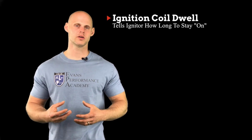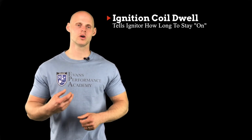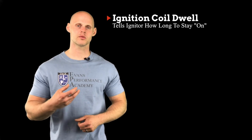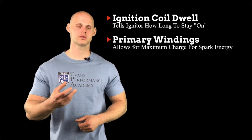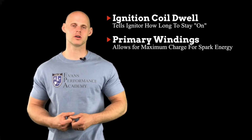So in this last part of the video, I want to talk about ignition coil dwell. Now the coil dwell is simply going to be the amount of time that the ECU is going to hold the igniter in a charged or on state so that our primary windings can charge up to that 7 amp point to release to the secondary windings to provide the maximum amount of spark energy to our spark plug.